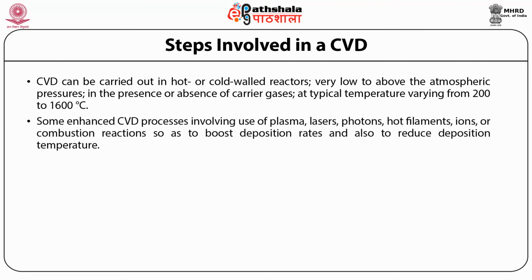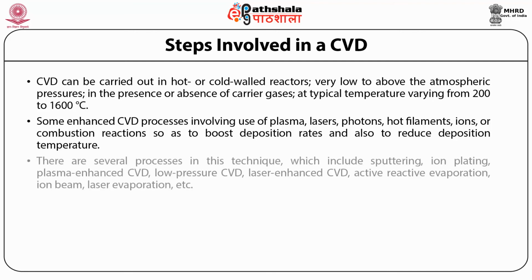Some enhanced CVD processes involve the use of plasma, lasers, photons, hot filaments, ions or combustion reactions so as to boost the deposition rates and also to reduce the deposition temperature. There are several processes in this technique, which include sputtering, ion plating, plasma enhanced CVD, low pressure CVD, laser enhanced CVD, active reaction evaporation, ion beam, laser evaporation, etc.